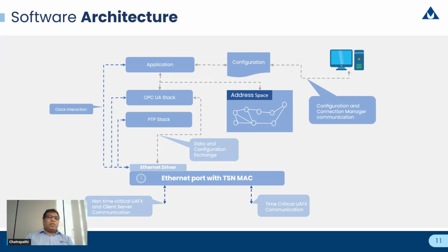And so the application or even OPC UA stack and then the PTP stack interact with the TSN clock data as well, and then the IO data and other data, and as well as configuration data related to TSN is exchanged between the stacks and the TSN MACs, and the connection manager communicates with the configuration data and application to establish connections and so on.